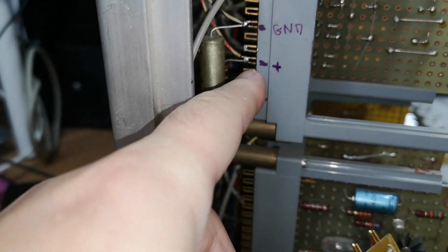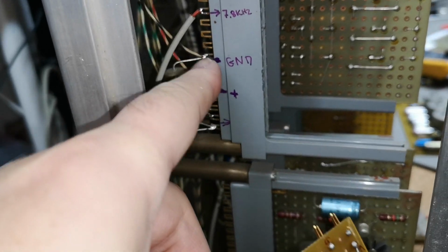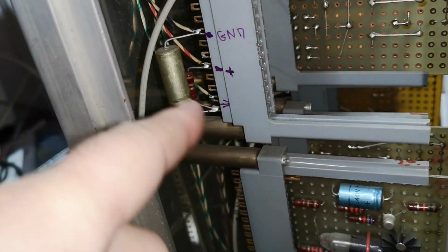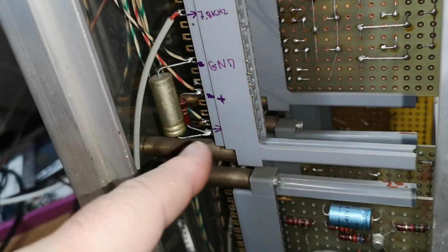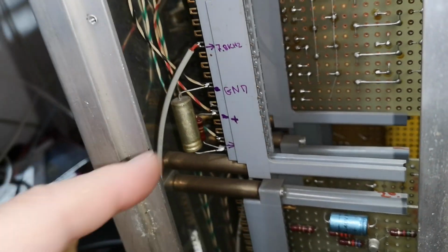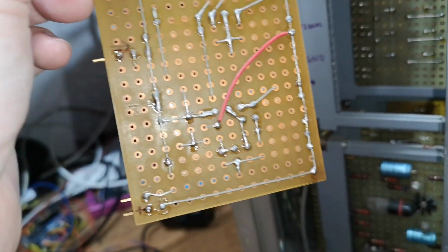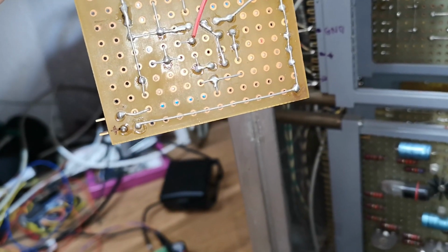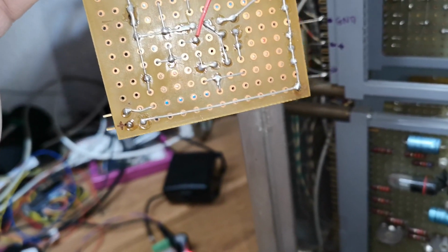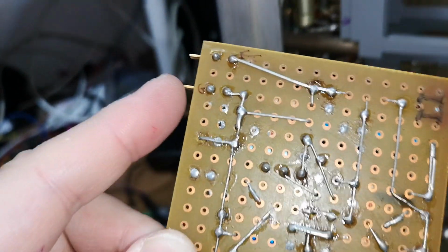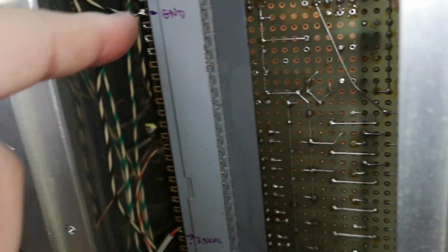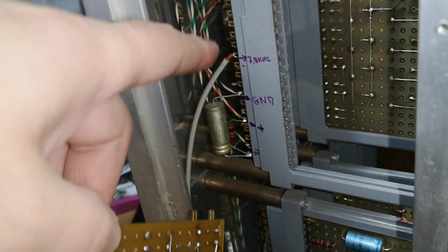They didn't even use this ground or this positive. This is only for holding the wire and holding this series resistor. They figured out they needed a series resistor and a capacitor for local isolation and filtration for this module. See, down here is the positive input, and ground is all the way up there. So this is ground. So that wire is actually connected down here for the capacitor. So that's what they're doing.